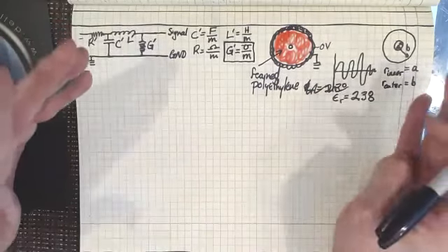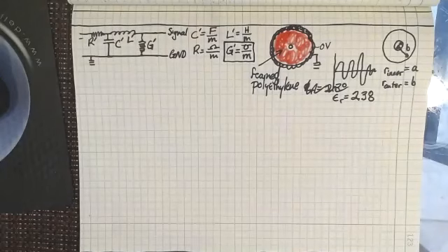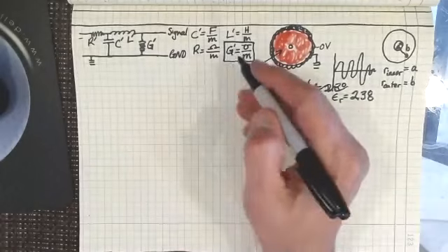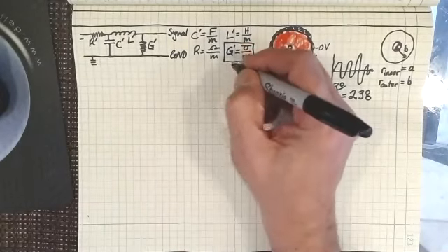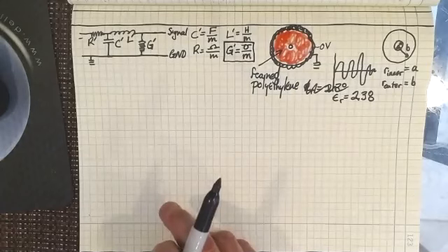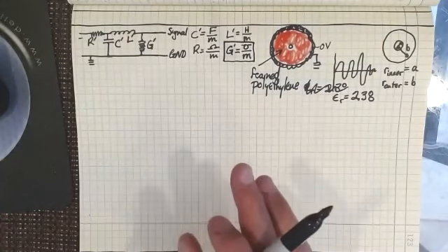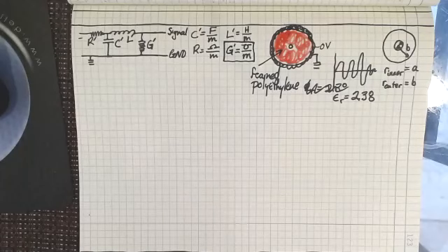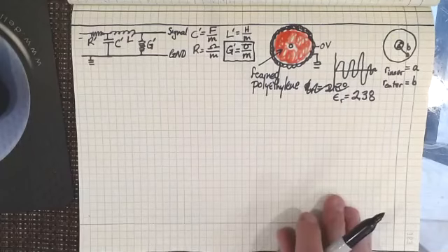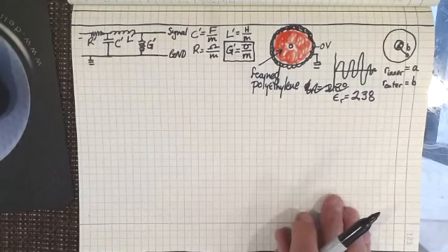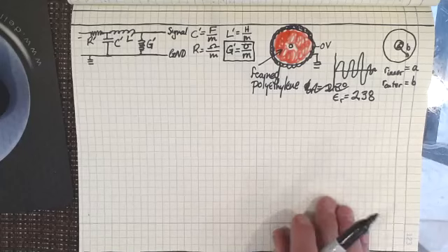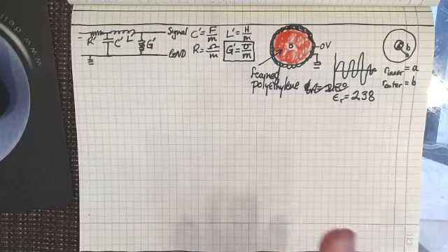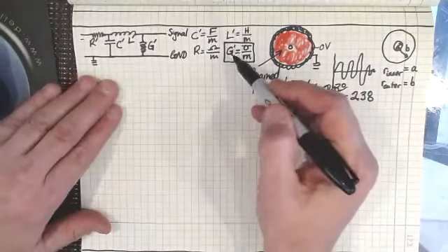Now, is there such a minor current? I mean, back years ago, would we have to actually use G in the telegrapher's equations back in the 1800s? Yes, because we're transmitting through the atmosphere that could be very moist and humid, right? So G then between two wires going through the atmosphere, you know, might actually have a significant value, even though that would even be small.